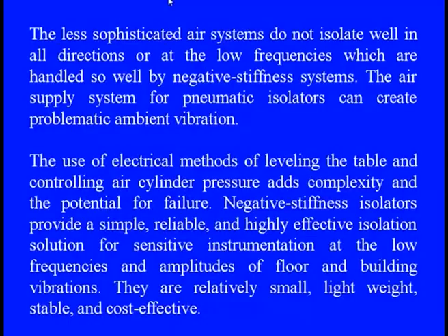And also we need to check what exactly the maintenance features are to keep the pressure uniform and at the same time the leveling of the entire system. So, the entire control strategy is somewhat expensive for such a sophisticated system. But at the same time, when we are dealing with low frequency excitations, sometimes this air suspension is not an accurate one.